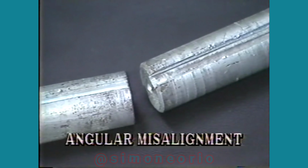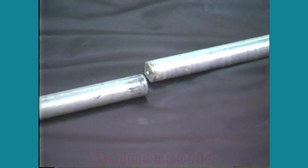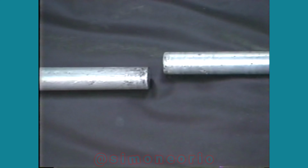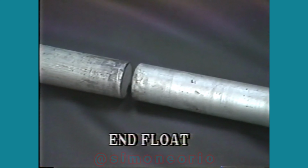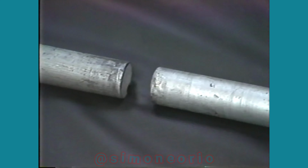Angular misalignment is where the two shafts are not exactly pointing in the same direction, like this. Parallel misalignment is where the two shafts point in the same direction, but are not centered one with the other, like this. End float is where the distance between the connecting shafts changes. End float can be ever-changing and can present an engineering challenge.